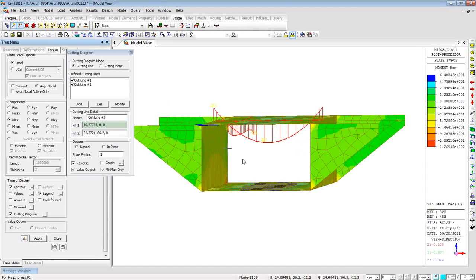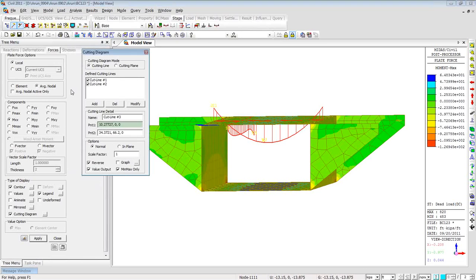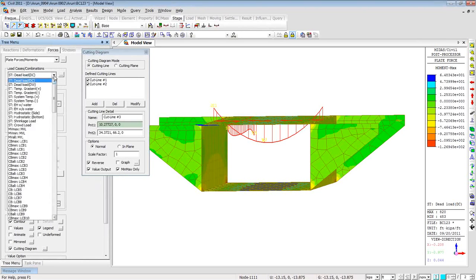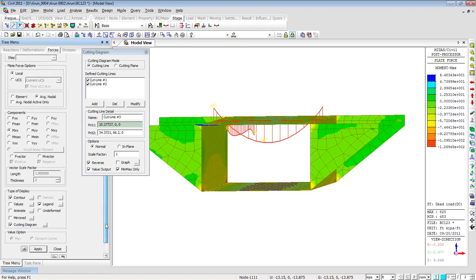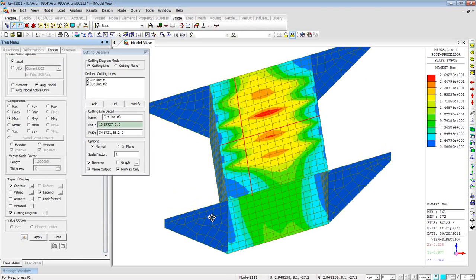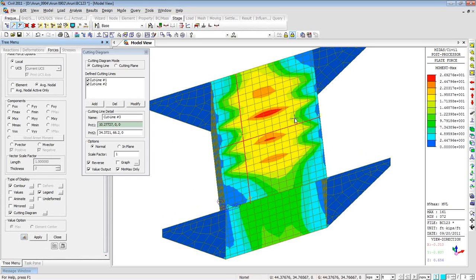And having done this, let me show you some live load results as well. So for the plate elements, you can choose, let's say, MV max, which means maximum positive bending moment envelope, and click apply, and this is what the program has generated. So this is the live load envelope contour plot, and I can choose any element and generate the loading pattern for that same.